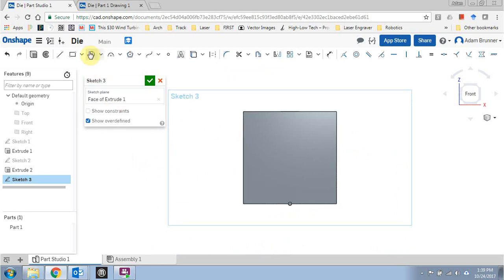I can continue around, making the front view here. I'm going to do the 2, and I'm actually just going to create 2 circles here really quick since I already have the tool active. I'm then going to create the size of them, so I'm going to set this to 1. I'm going to set this one to 1. And then with my dimension tool, I can click on the center of the circle to the edge, and I can set this to 7/8. So you can see it actually does fraction to decimal for us. If you wanted to type in 0.875, feel free to.